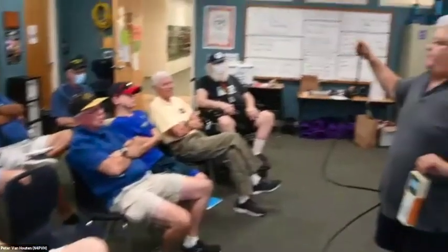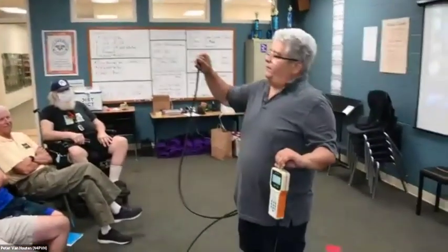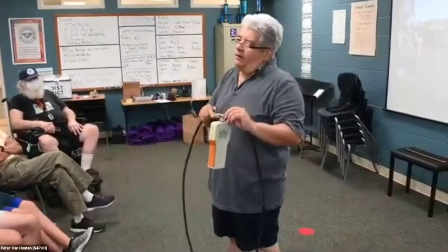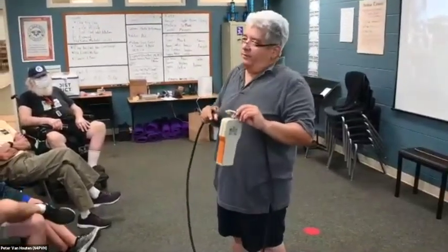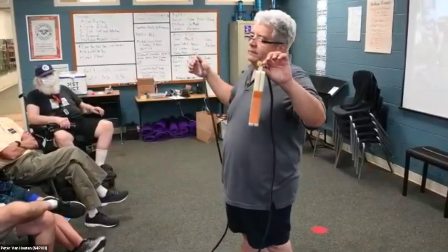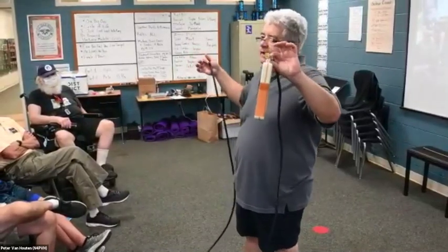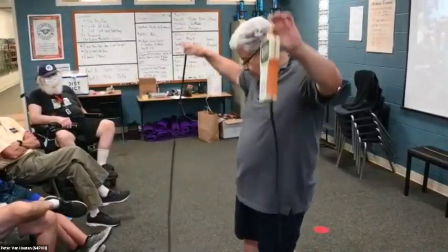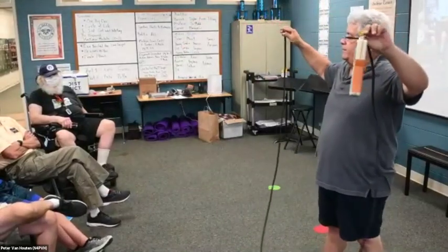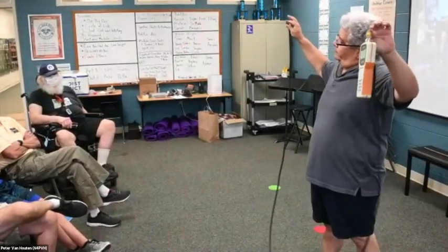Now I could put a short here. You short this end and go down to 14.2 megahertz, and it should be the same. It should give me a quarter wave length on 20 meters, or what we are measuring here, half wave on 10 meters. This is quite simple to do.